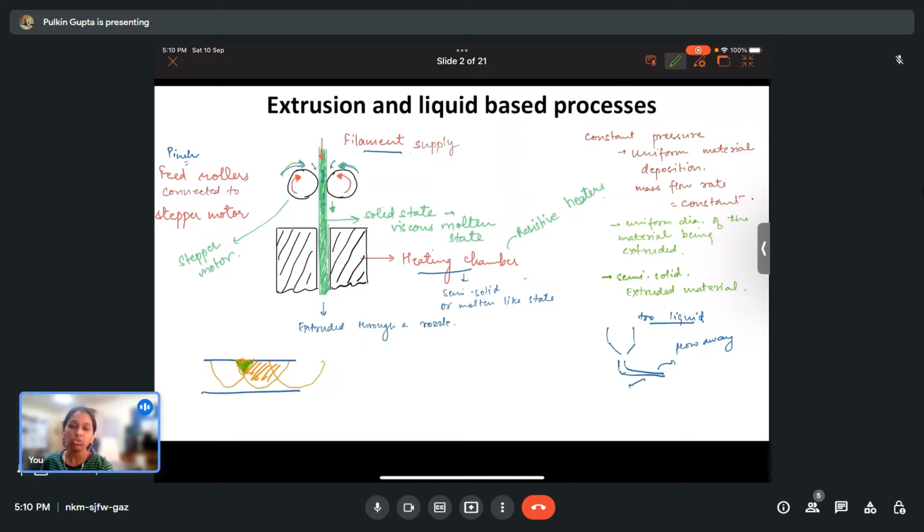And why is it so? So as to ensure good bonding with each other. Similarly, the extrusion should be made in such a way that the newer incoming material solidifies or bonds with the already existing solidified material on the substrate, so that you have a solid structure.